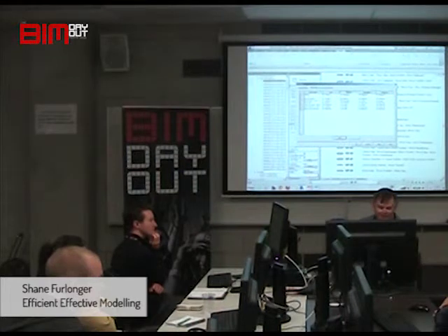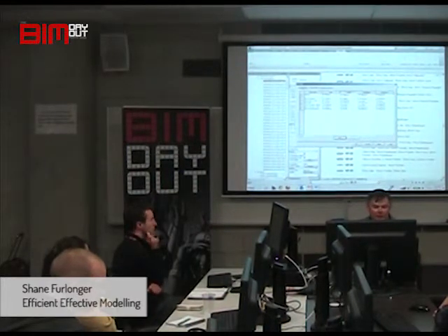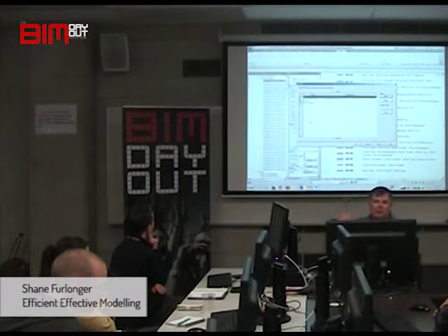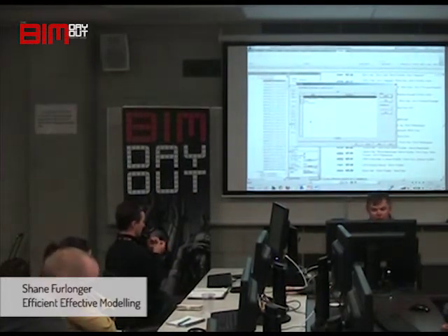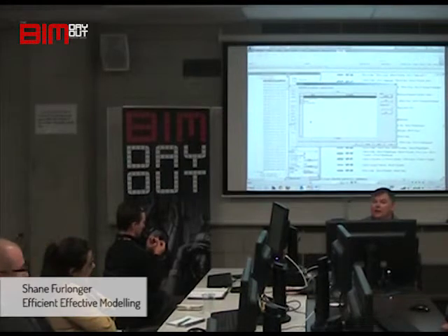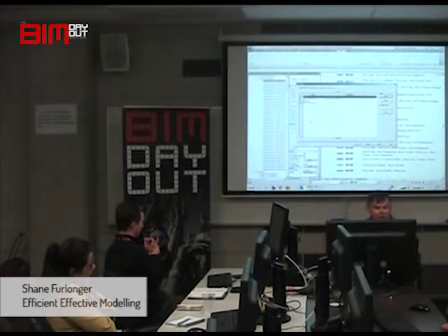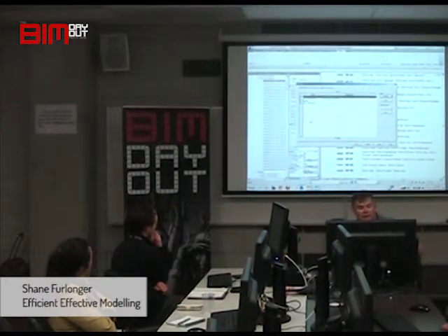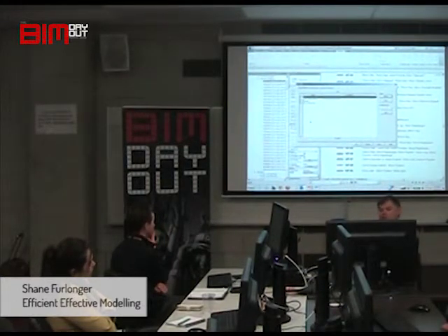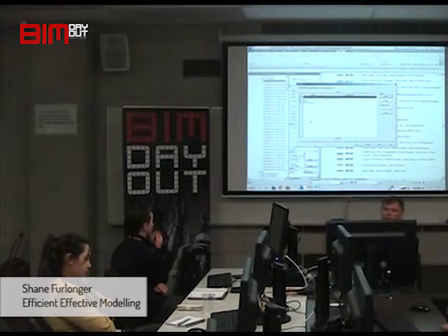Sort of. So just remember this bit at the start, and Revit, when you first start up with what comes on the system out of the box, will have existing and new construction as their initial phases. And you think existing, okay, that makes sense. And then you look at the phase filters and it says new, existing, whatever. You think, oh, it's got to relate to the one before, and that's when you start getting confused. So existing in this instance means for me that it was whatever existed before the building started.